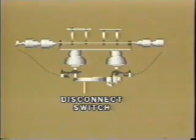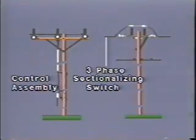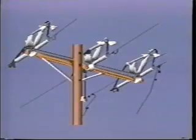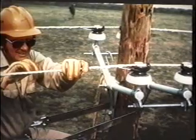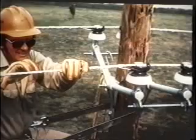A wide variety of switching equipment is used on distribution circuits, ranging from this simple hook-stick switch on single-phase lines to the use of group-operated switches on a three-phase sectionalizing point. On this particular installation, the three primary conductors are dead-ended into the switch bases. The entire three-phase line can be switched by operating the control assembly to isolate, reroute, or pick up a section of line. This videotape has emphasized the overhead distribution portion of the power system.